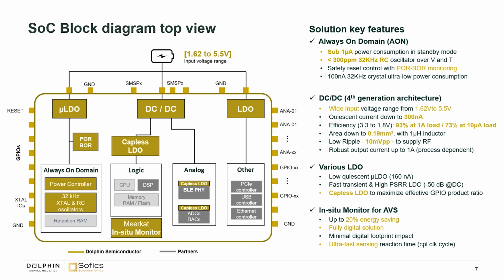So you will have some flags, and then when you reach the limit, you're going to have some flags or maybe an alarm, and then you know that you have somehow overclocked, if I can say it like this, the device. But it works also the other way around. You may say, look, I'm happy with the performance, now I just want to reduce the power in order to increase my power saving. Therefore, you're going to reduce the voltage of the digital and still monitor those flags and error signals in order to say, okay, this is the lowest level I can reach in powering the logic with still an acceptable performance and without any degradation of the signal.